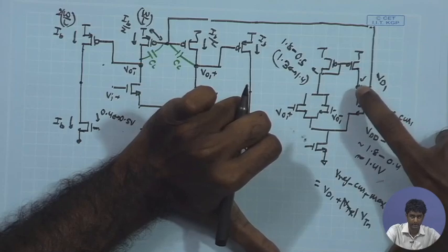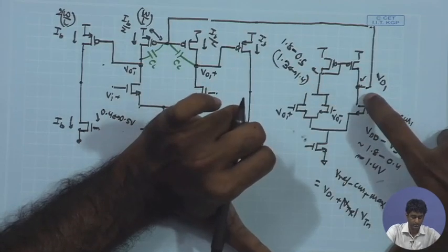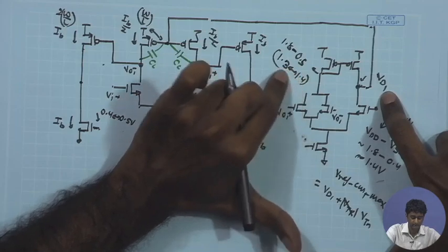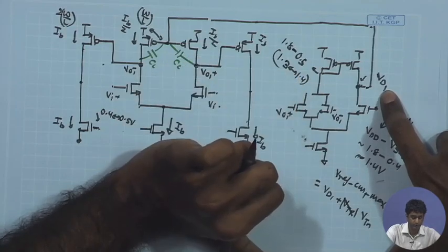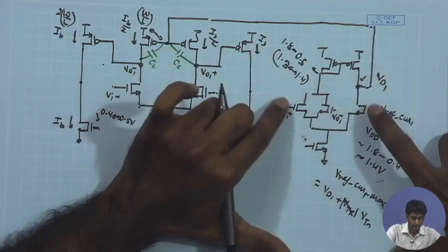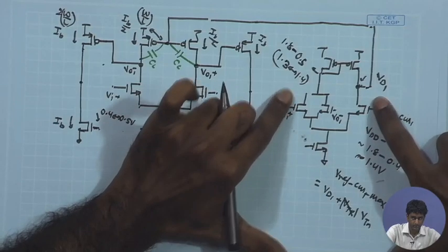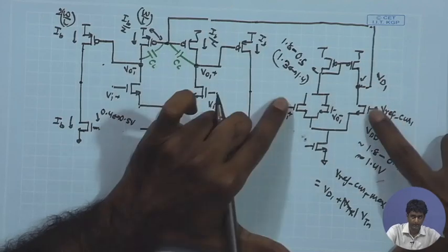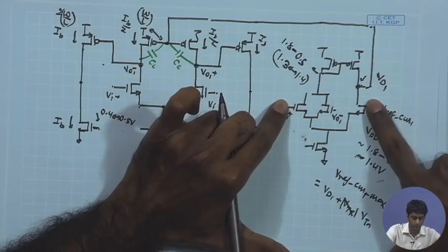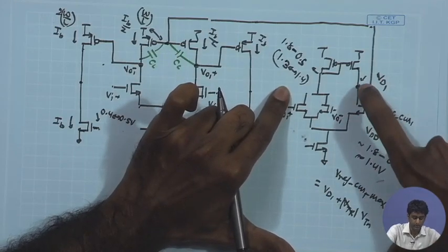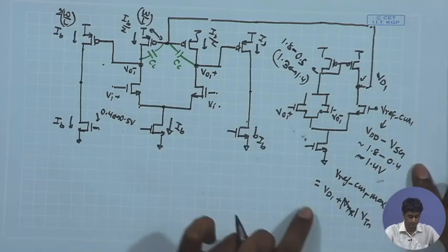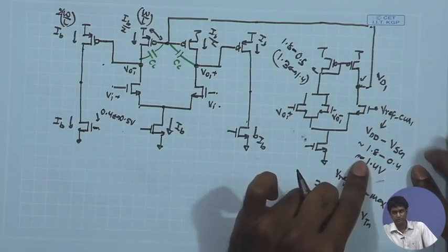So, I am assuming that under nominal condition, under steady state operation, the Vd1 is having a value close to 1.3, 1.4, and under that condition the maximum input level, the maximum common mode level for this amplifier, or in other words the maximum reference common mode level that you can have for this is going to be the Vd1 plus Vtn, which is once again 1.3, 1.4 plus the Vt.